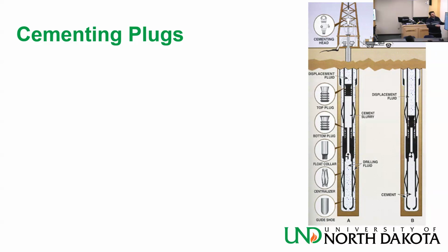We are going to talk about it. It's normally colored red or orange. It is important. And then the top plug is colored black or yellow. Okay, and the sequence in which they go through the well is important. If you get a very bad employee who puts the top plug in first and then the bottom plug, you basically lost the well. We'll explain why.